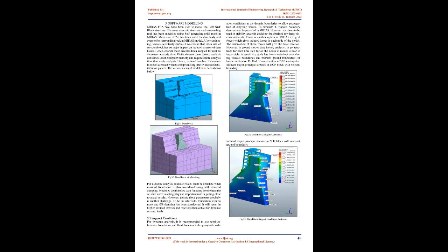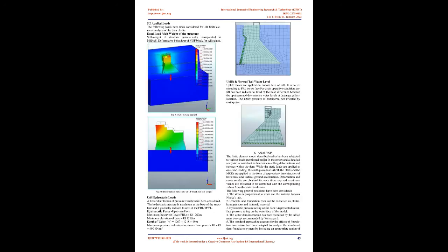Foundation load distribution can also be sensitive to the value selected for foundation modulus, which can affect foundation sliding stability calculations. Therefore, it is important to make good estimates of the potential range of foundation modulus values. Since we have deformation modulus of rock from jacking test, 80% of E-concrete may be considered. E-foundation dynamic equals 80% of E-concrete, i.e. 20 GPa, has been considered in the present analysis.